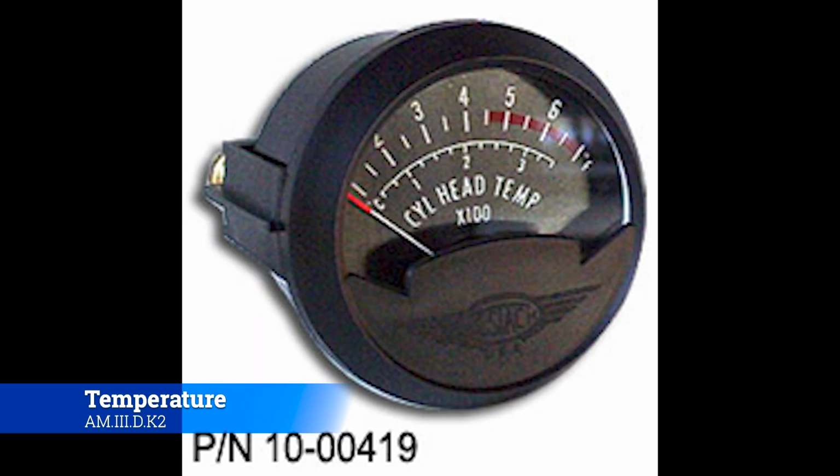Okay, the next one we want to talk about, and the last one in terms of temperature, is going to be the cylinder head temperature. Now this is something that's unique to just recip engines. So we want to know what is the temperature of the head of the cylinder, so the very top of the cylinder. What's it running at? Is it running in 200, 300, 400 degrees Celsius, which is what this gauge is actually set in? And what does that tell us?